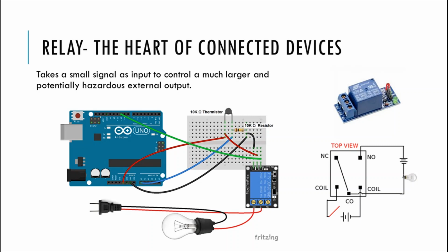Now, as I told you, we're going to be talking about relays. Now, the Arduino cannot supply 15, 20, 30 volts, which is generally the norm for most devices. So for example, if you're looking at the night lamp example that we just did, if you really wanted to connect it to a lamp, these lamps deal with, based upon the country you're in, 200, 220 volts on a regular basis. Now that cannot be provided by the Arduino. So what we do is, we connect this to a relay. As shown in the diagram, a relay has 3 pins.